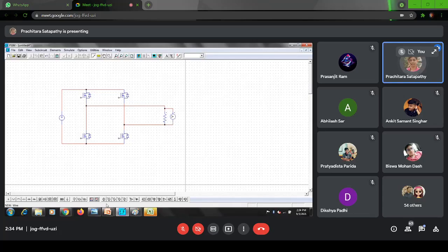You cannot connect the gate pulse directly, so you have to use a normal on off switch. After the pulse generator you have an on off switch. So the comparator output will be given to the switches through an on off switch. To every switch you connect that. Clear?